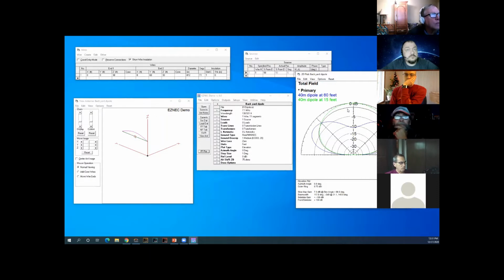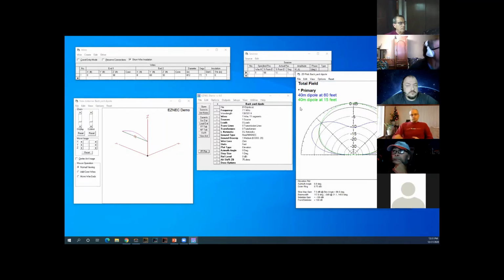Everything's going straight up in the air. And a little comment, by the way: everybody says, oh, my antenna is NVIS. The ionosphere doesn't reflect anything up here. The ionosphere bends. It's not a mirror. So when you're shooting straight up, you're talking to the aliens up there, which maybe Kurt's pretty good at, but the rest of us are not. So yeah, NVIS, you don't want it. They don't work.